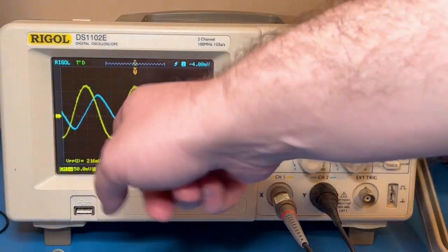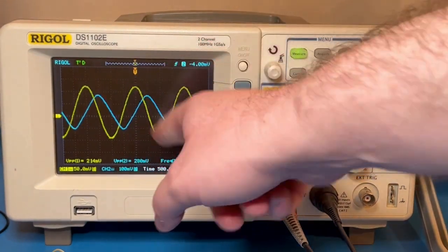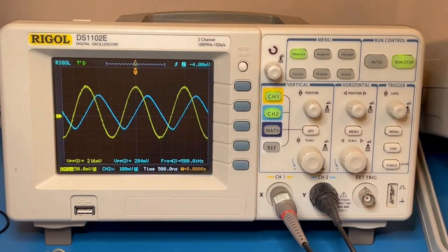We can also note that there's a sharp bottom and sharp top, and the two sides of the waveform appear to be more flat and less gradual, like a proper sine wave. This is a form of distortion that appears to be occurring due to the high frequency. This is very likely what's called slew rate limiting, which is an effect we will explore in later videos.